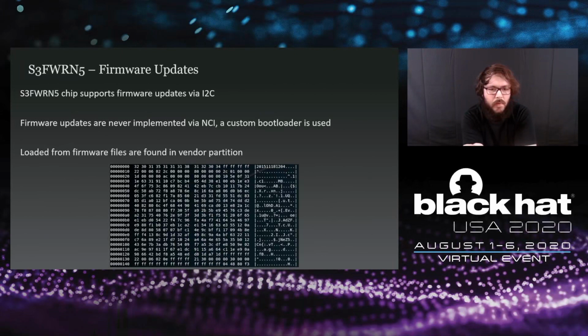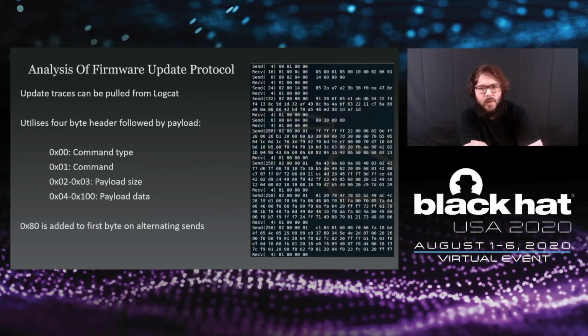The device itself was found to set whether it was in bootloader for firmware updates or regular mode via a GPIO input, which could be set via the driver. And I found that when you switched it into bootloader mode, it had a slightly different protocol than NCI, but only slightly different. What this was used for was to differentiate itself from NCI in order to allow the vendor partition and the vendor implementations of certain aspects of the firmware to update this chipset and use it to do different things. This firmware update protocol was quite simple.